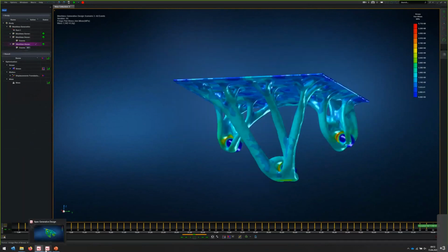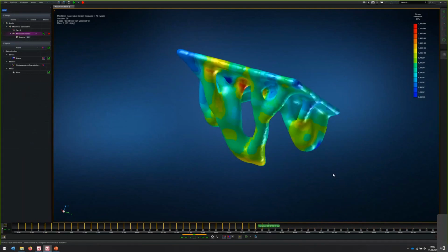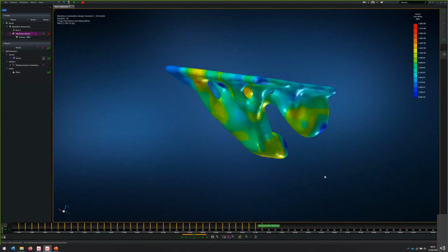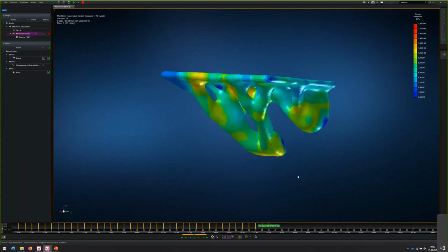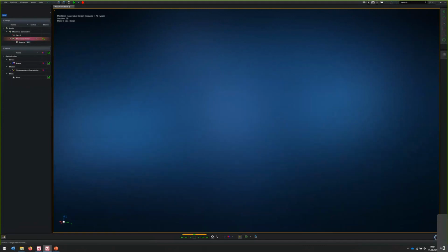Okay, now we will switch back to our model we just set up, and we see that we are already at iteration 39. I think for the time's sake, we will stop this iteration, and to show you this as well, you can terminate the simulation up here. And it will take a moment because the iteration will run till the end. And whenever this is finished, the status bar will update just as it happened now. The simulation is terminated. And after it's terminated, you can exit the post-processing.